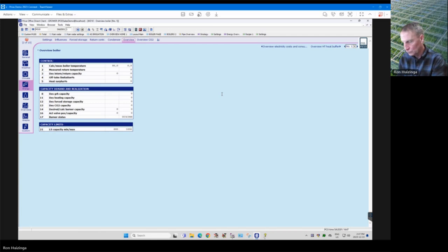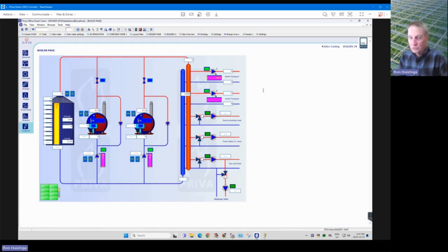Okay, thanks, Ron. Another question here: when the height of the buffer goes down, is refilling manual? Typically, yes, but there are some large customers that have constant leaks somewhere, and they have automated it, so it's kind of scary. But normally that's manual. Usually there's a manual valve that's either plumbed in already, or you have to hook up a hose to fill up the water in the system again.